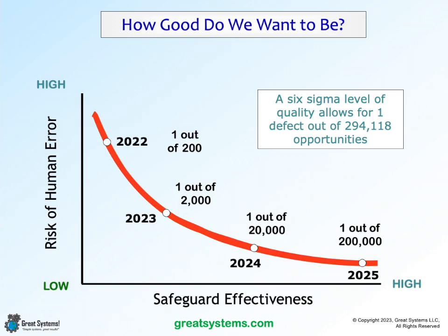If you think about lockout, tagout, where we're isolating processes and removing energy from processes, and we're working with very flammable stuff under very high pressure, imagine the potential for problems if a person misses a point of isolation or isolates the wrong place within the system. And so we expect very low error rates with folks like that.